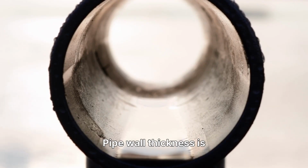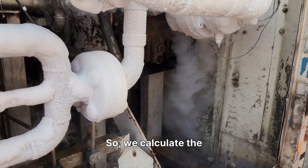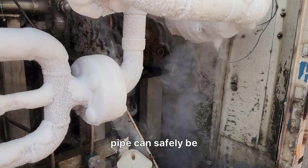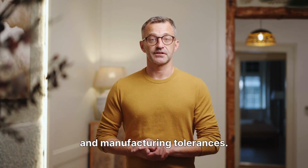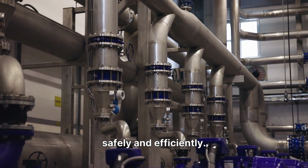Pipe wall thickness is one of the most critical design factors in any plant. A small error can lead to leaks, ruptures, or catastrophic failure. So, we calculate the minimum required wall thickness, the thinnest the pipe can safely be under internal pressure. And then we add safety margins for corrosion and manufacturing tolerances. That's how engineers make sure every pipeline runs safely and efficiently.